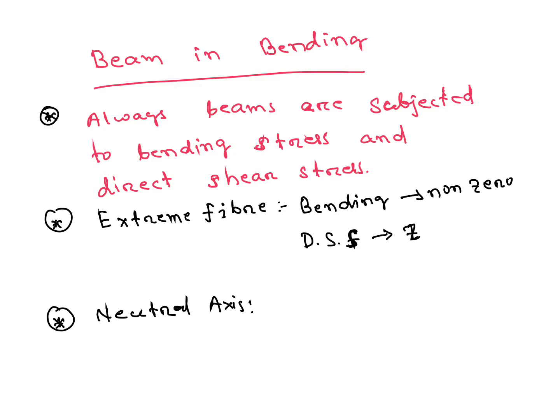This is very important. Bending stress is non-zero and direct shear stress is 0 at extreme fibers in case of a beam subjected to bending.